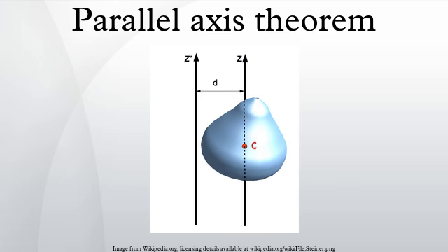Recall that the center of mass R has the property where r is integrated over the volume V of the body. The polar moment of inertia of a body undergoing planar movement can be computed relative to any reference point S, where S is constant and r is integrated over the volume V. In order to obtain the moment of inertia I_S in terms of the moment of inertia I_R, introduce the vector d from S to the center of mass R. The first term is the moment of inertia I_R, the second term is 0 by definition of the center of mass, and the last term is the total mass of the body times the square magnitude of the vector d. Thus, I_S = I_R + md², which is known as the parallel axis theorem.